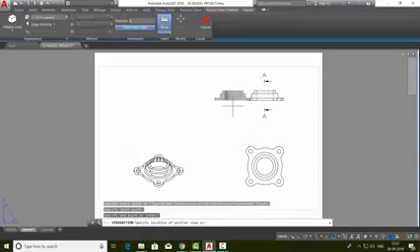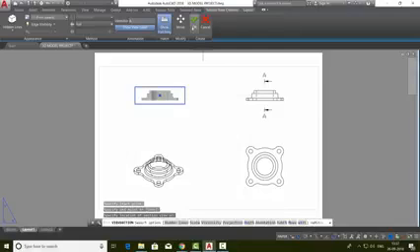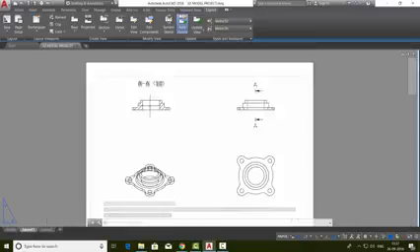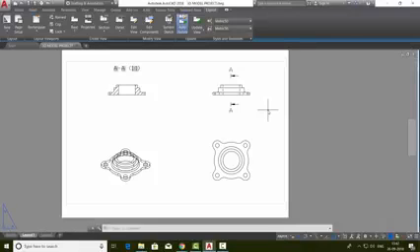Now you can keep the sectional elevation in a convenient location. I'll make a click here and just give OK or enter. This is a sectional drawing and the scale is also written. You can also change the various properties and parameters related with these views.